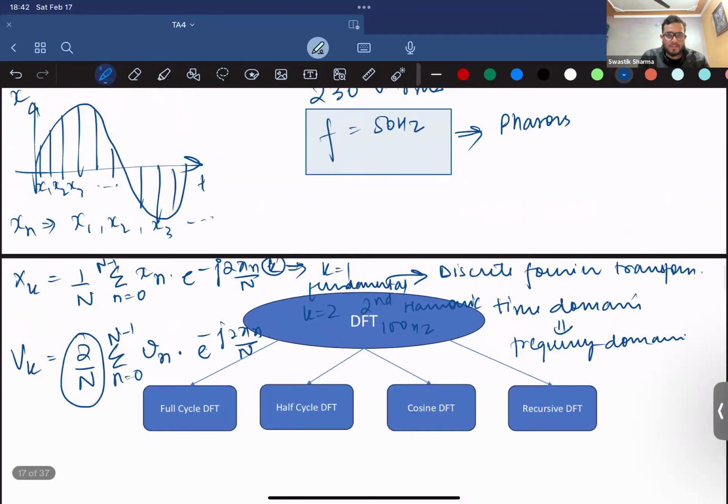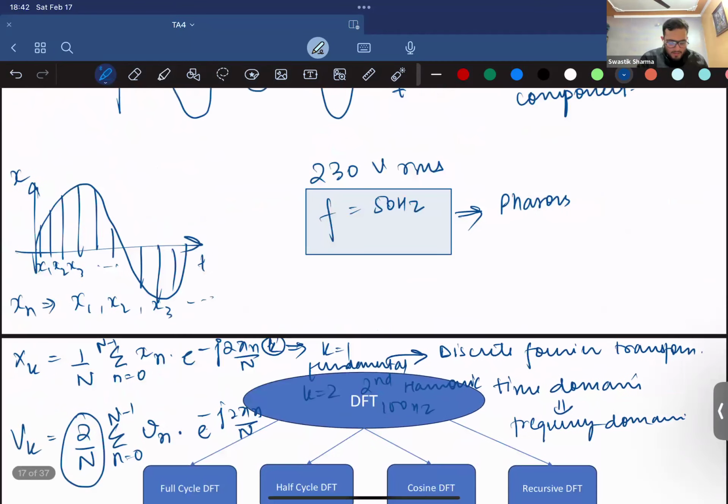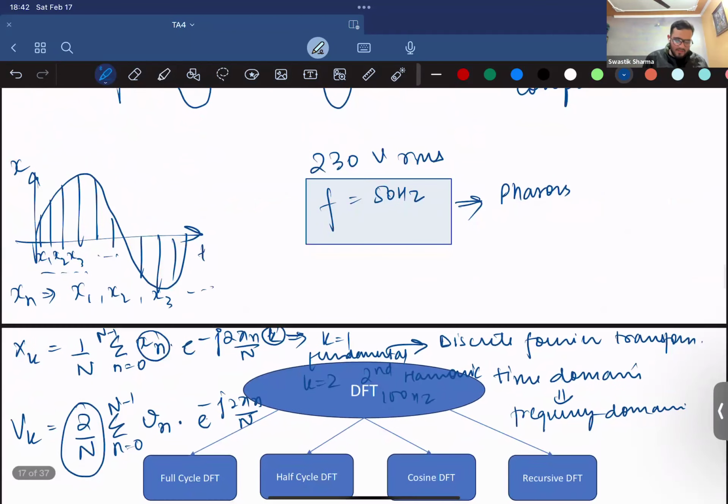So it's called discrete because you are taking discretized samples of your time signal, right? You're sampling it with discrete signals, so this xn is discrete. That's why it's called discrete Fourier transform. So why are we scaling it with 2 by n? She didn't explain it in her slides, but you must have had this question if you watched the lecture. I hope that you watched. So can anyone tell me why this scaling of 2 by n is coming into play?